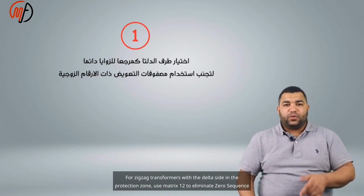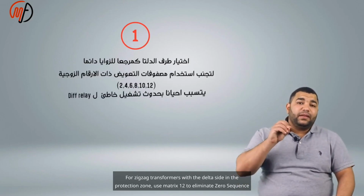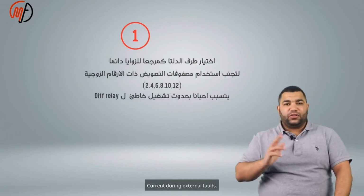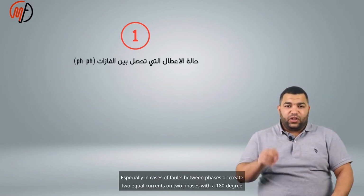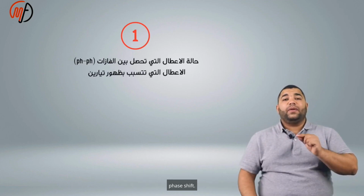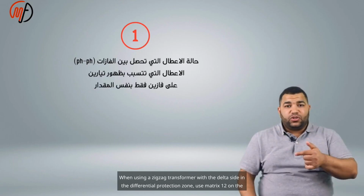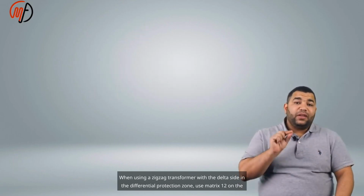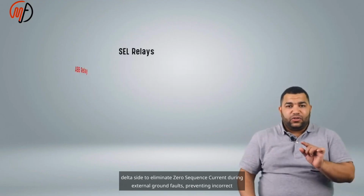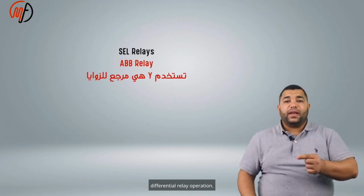For zigzag transformers with the delta side in the protection zone, use matrix 12 to eliminate zero-sequence current during external faults, especially in cases of faults between phases or that create two equal currents on two phases with a 180-degree phase shift. The AB relay uses the star connection as the angle reference. When using a zigzag transformer with the delta side in the differential protection zone, use matrix 12 on the delta side to eliminate zero-sequence current during external ground faults, preventing incorrect differential relay operation.